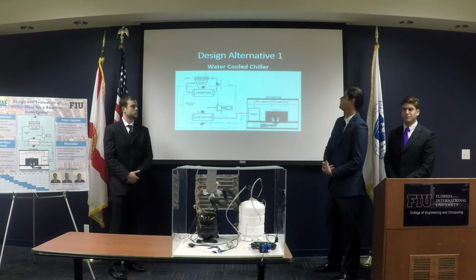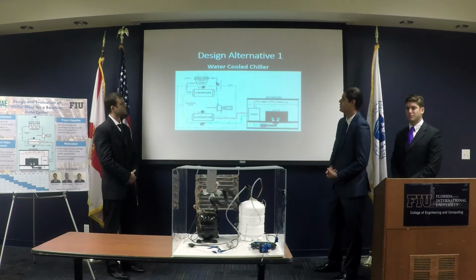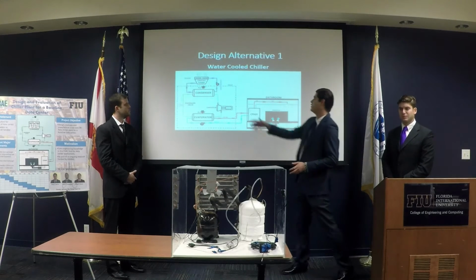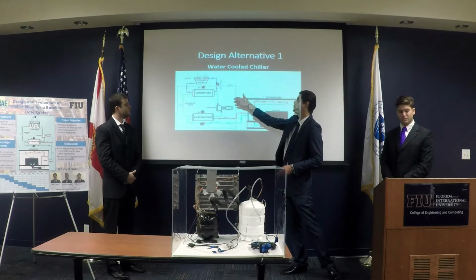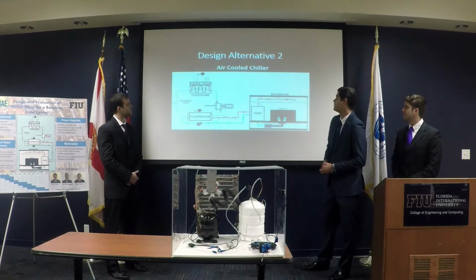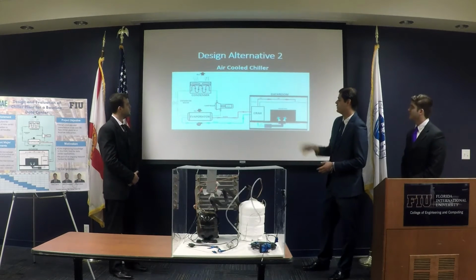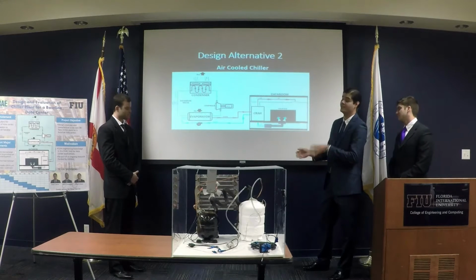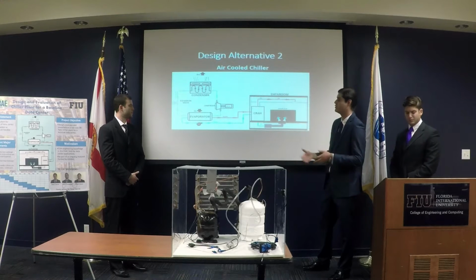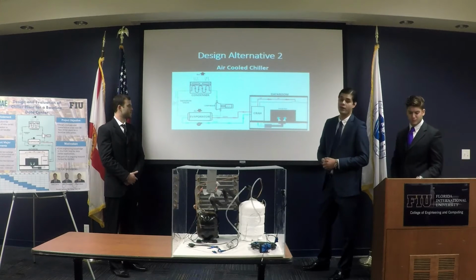So this is our first design alternative, a water-cooled chiller. We didn't select this one because it was the most expensive one, because it uses a cooling tower, an additional pump, and additional piping. The other design, which is the air-cooled chiller, this is the one we selected. It's not as expensive as the water-cooled chiller, and it is also more stable than a computer room air conditioning unit.